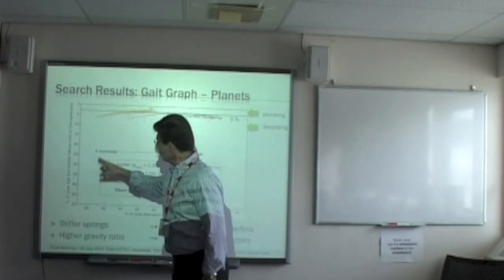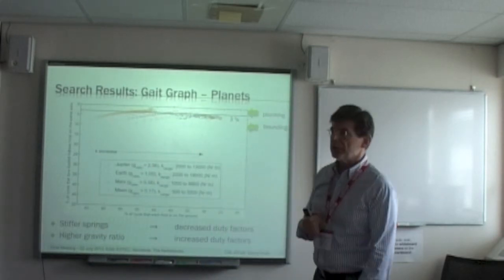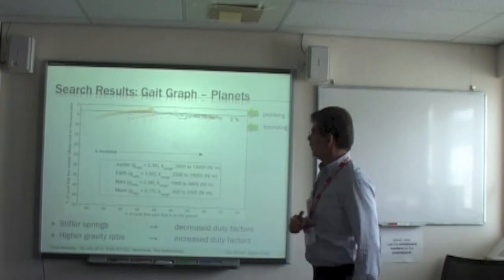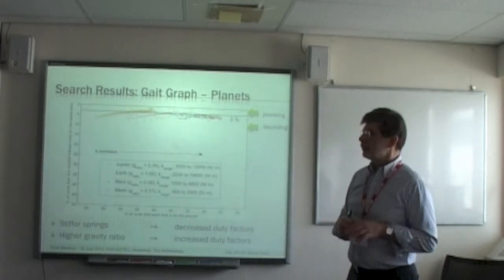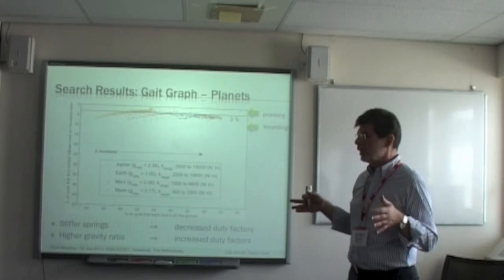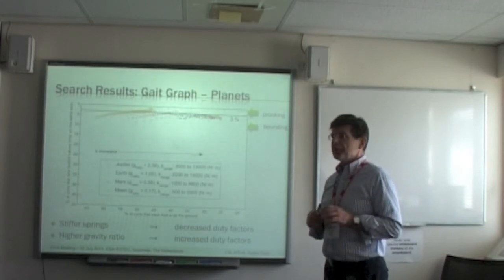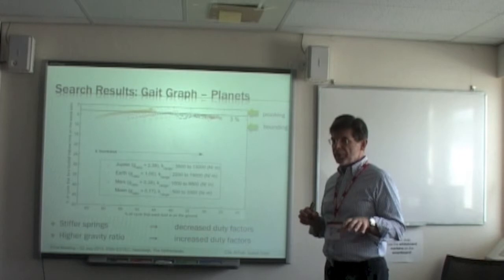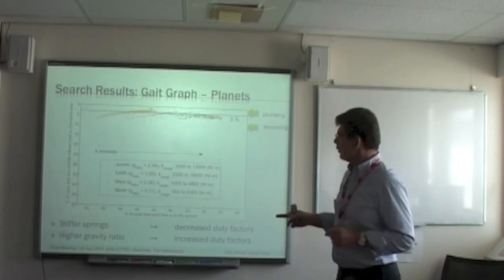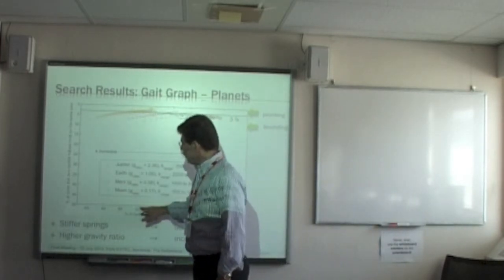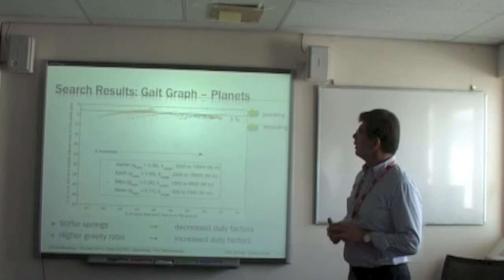perhaps I should say that before doing this, this axis here indicates the phase difference, and this one here indicates the mean duration that the legs stay on the ground. But this is a mean, because one leg may stay more and the other one may stay less, so we take the mean. So this is time on the ground, and this is difference between legs. So with this we can classify the gaits.